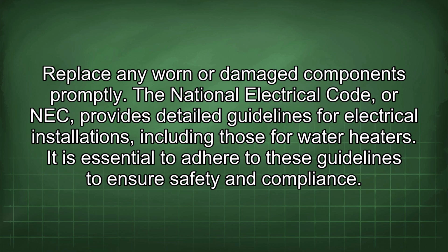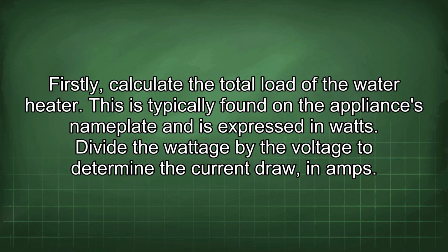The National Electrical Code, or NEC, provides detailed guidelines for electrical installations, including those for water heaters. It is essential to adhere to these guidelines to ensure safety and compliance. Firstly, calculate the total load of the water heater. This is typically found in the appliance's nameplate and is expressed in watts. Divide the wattage by the voltage to determine the current draw in amps.